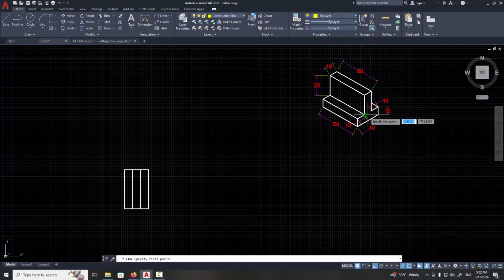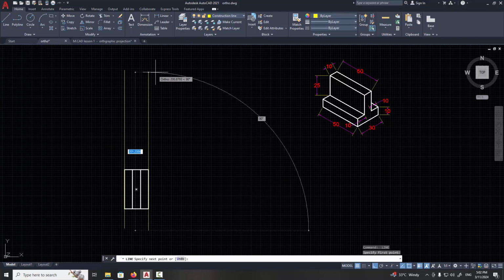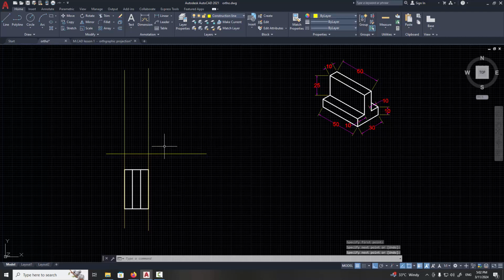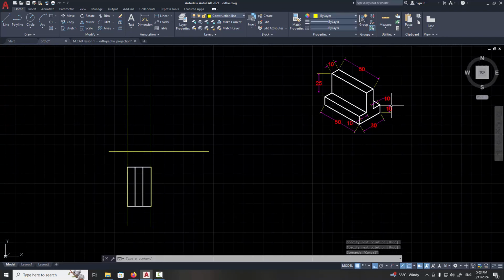And we are projecting this view using the top view we drew, since this bottom line is the front side of the object. So extend a construction line from the left corner of the top view going upwards, and do the same with the right corner and extend. Let's draw a horizontal line as the base. So once we have established the base, let's check the front face dimension, and you will see here it's 10 units high. So select the offset tool, then type 10, and then offset from the baseline upwards.